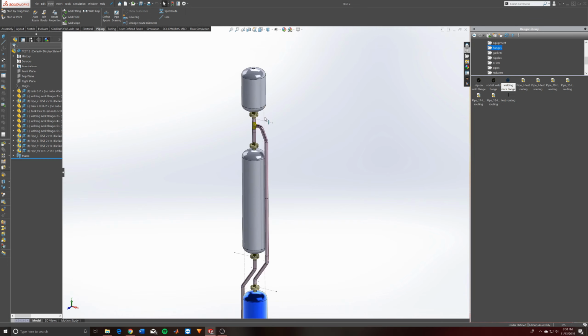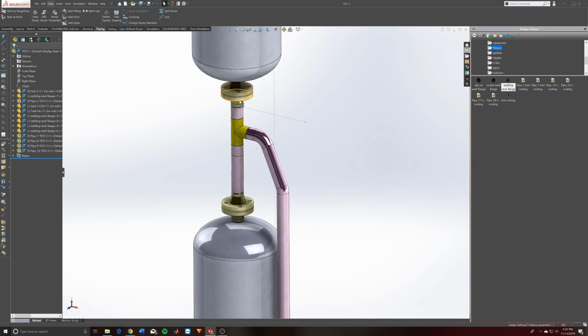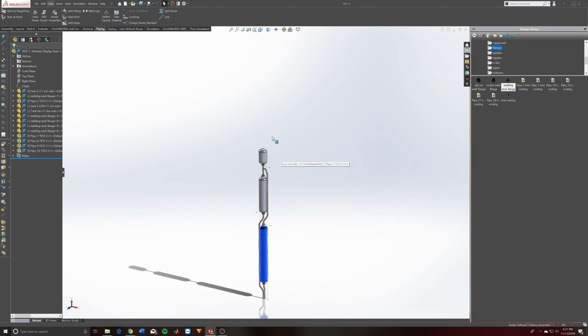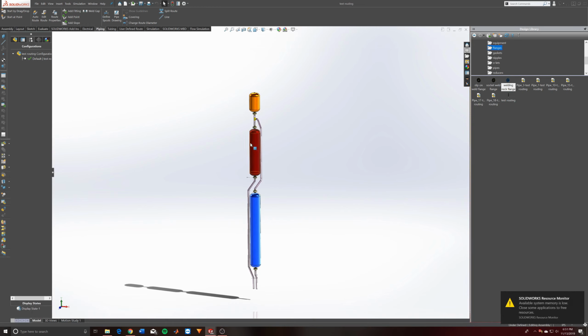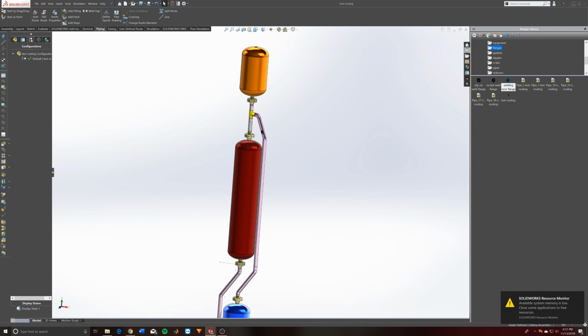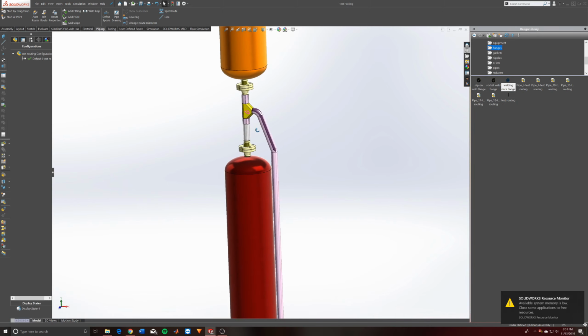You can change the thickness of your piping, and the diameter, the internal diameter, all that kind of stuff. That's going to be nice, especially once you create a rough model like this. You'll be able to change it however you want later on, so you won't have to go back and do it all over again. But for now, that's a great way to get you started.